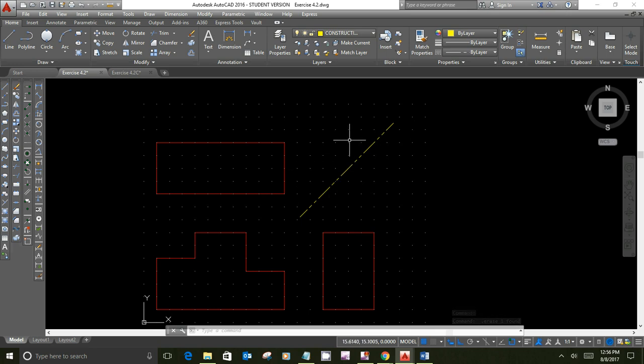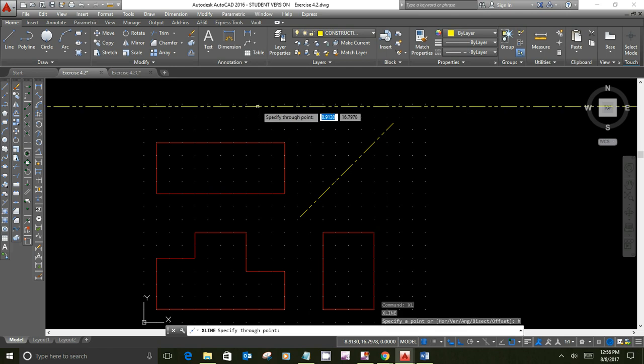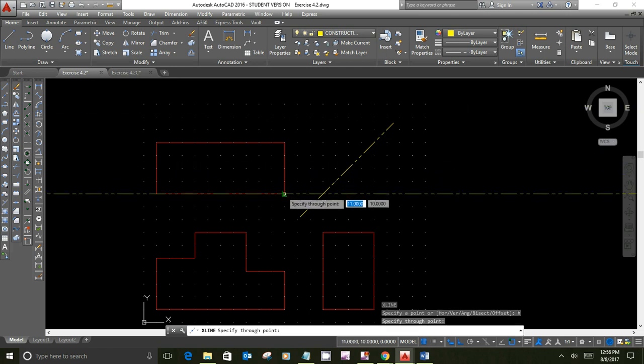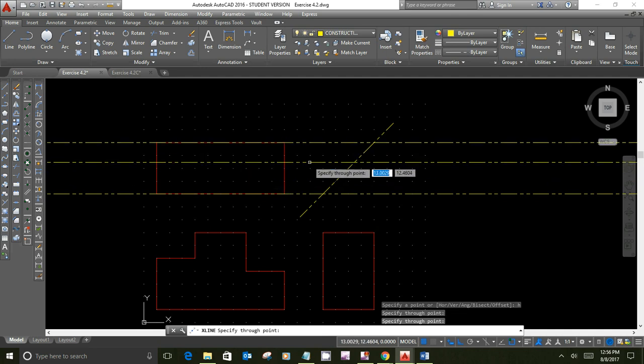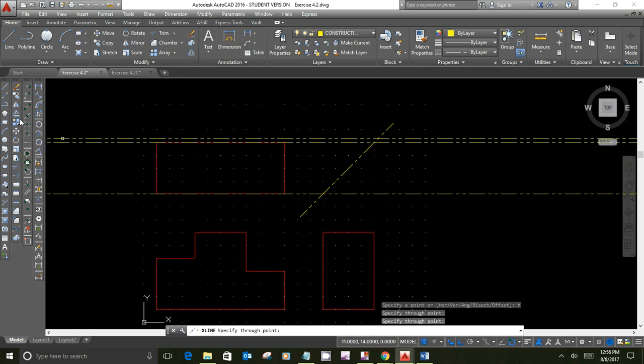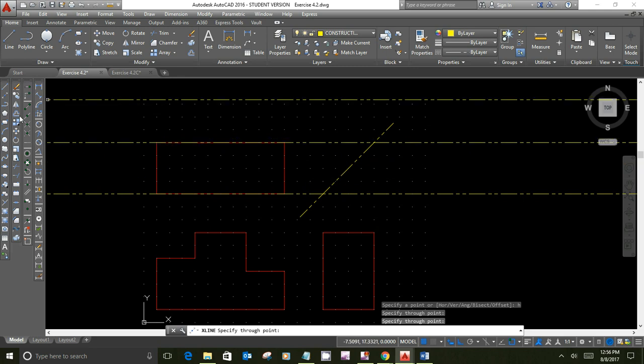So the way that we would use this, in doing drawings, if we're using construction lines a lot, and I'm going to say horizontal construction line. If I put one here and I put one here, and let's just say we had something in the middle here. I don't have anything snapped to, so we'll go to a midpoint object snap.